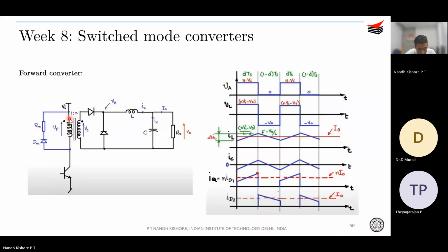So the entire Vin will appear across your primary side, that will get transferred to the secondary side as N times Vin, and that is what forward biases this diode and appears over here. Okay. And one more thing is we have to provide a path for the flux to actually go back to zero, right? And that is what is known as a demagnetizing path over here, correct?